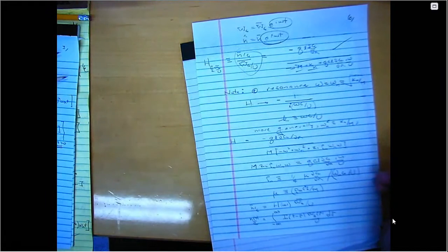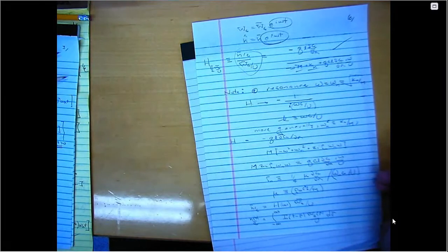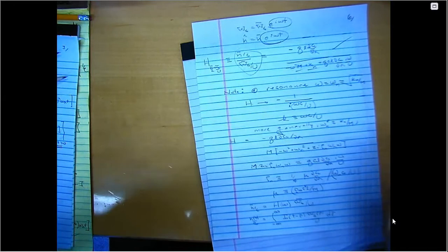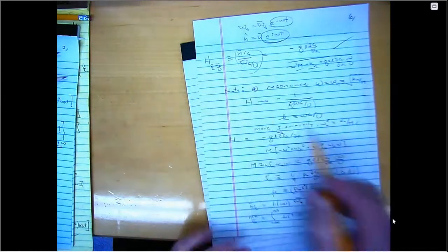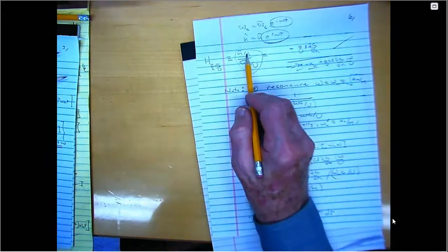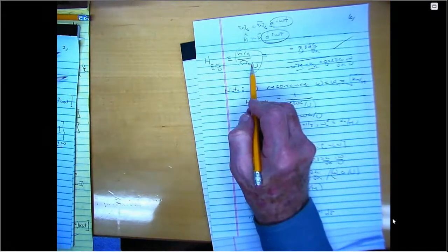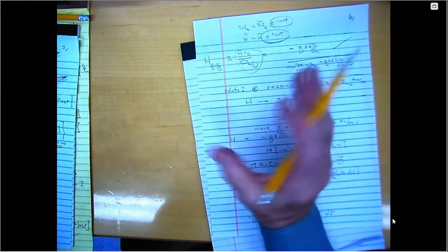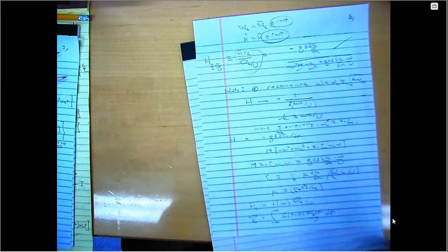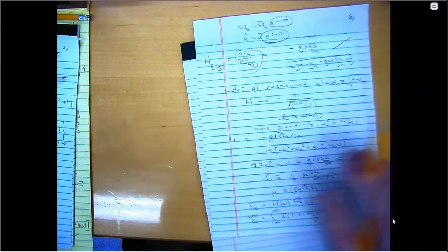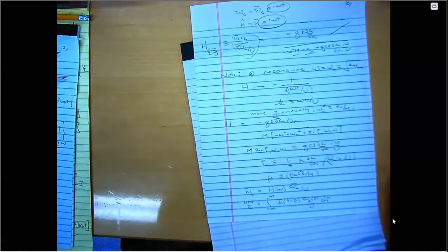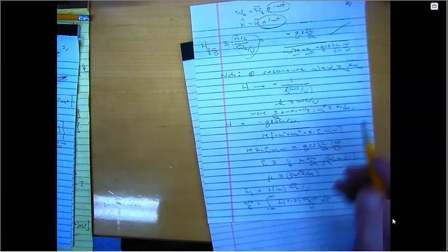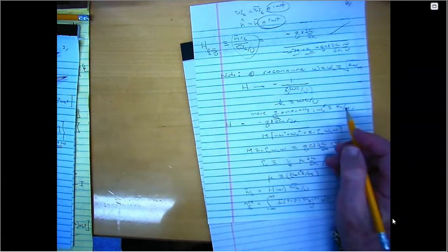Notice when the Strouhal number gets small, this thing gets large. When the Strouhal number gets large, this thing gets small. What does the i mean? It means that the response is 90 degrees out of phase with the input. That's all. That's just talking about the phase shift at resonance. Okay. More generally, we can work this out in a form that aeroelasticity likes.